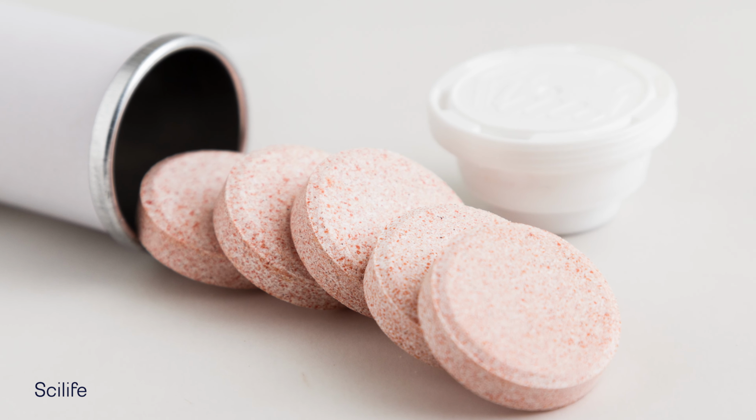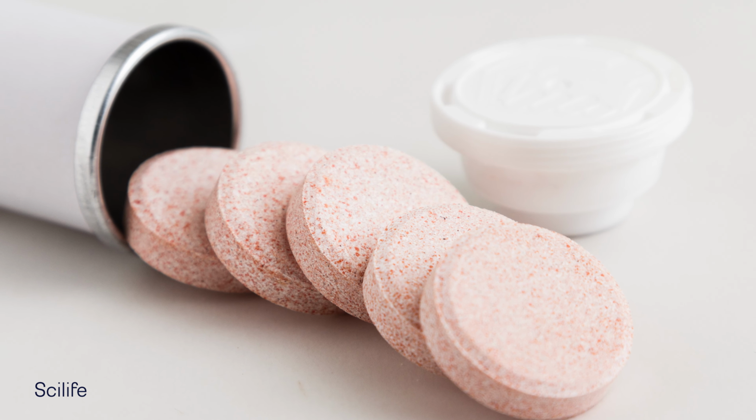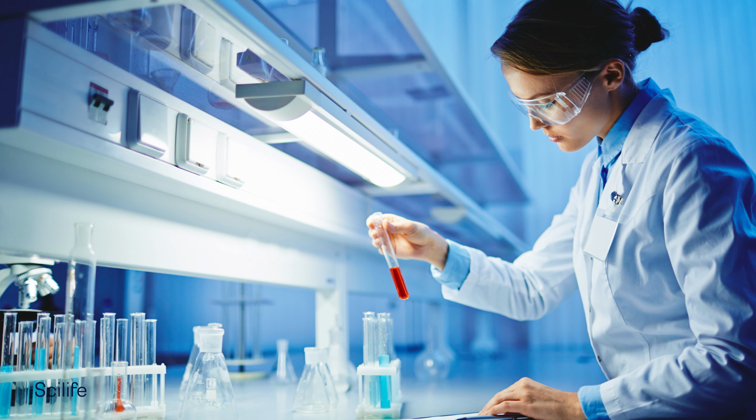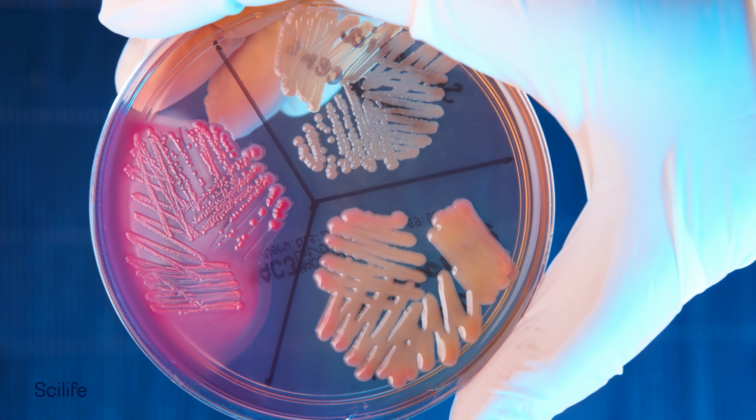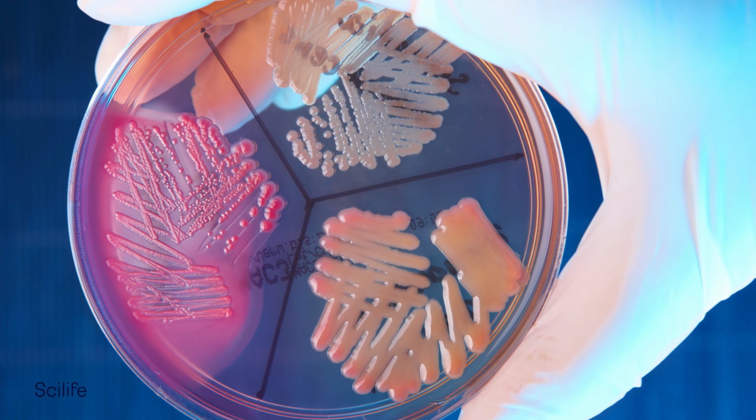Physical contamination includes particulate contaminants that can be suspended in the air or deposited on surfaces. They are typically measured in terms of particulate count per cubic meter of airspace or per square foot of surface area. Chemical contaminants include volatile organic compounds, gases, and other chemicals. They are typically measured in terms of parts per million or parts per billion. Microbial contaminants include bacteria, viruses, and fungi. They are typically measured in terms of colony-forming units per cubic meter of air or per square foot of surface area.